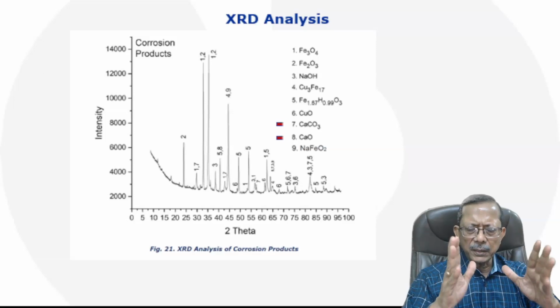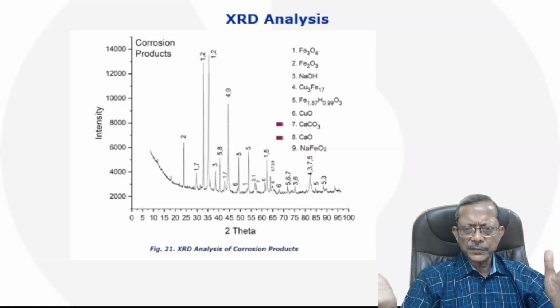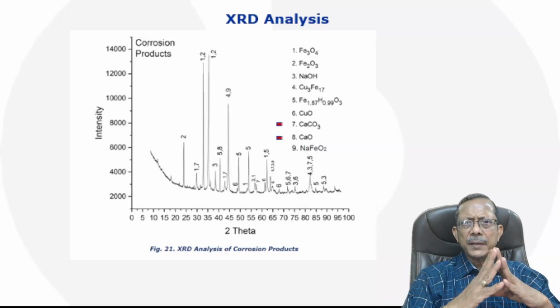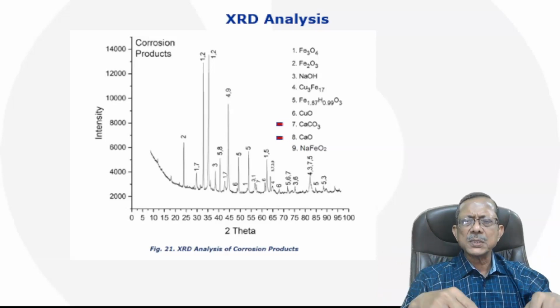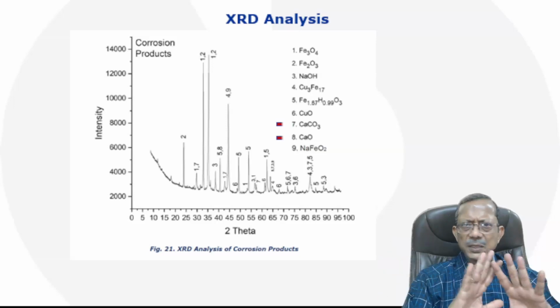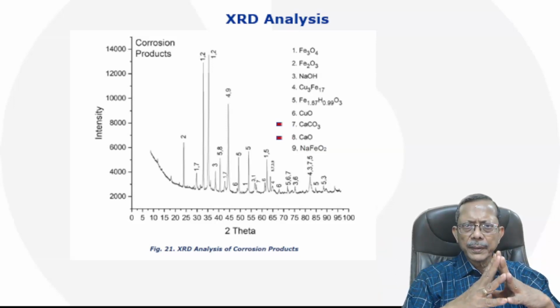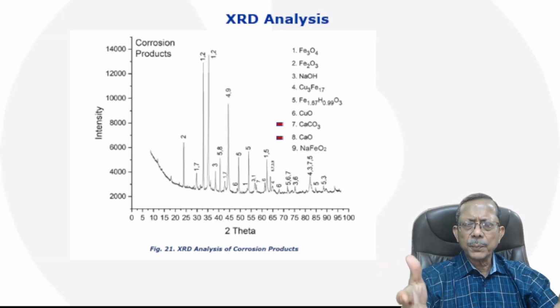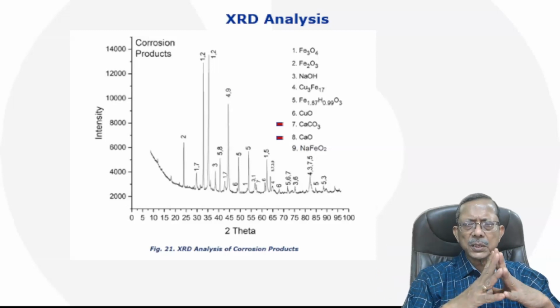So I need to find out the location from where this hardness is coming, where the copper and zinc are coming from. And if calcium is coming into the system, there will be deposit, there is no doubt about it. Below the deposit, there is a chance of, again, corrosion, and particularly with the conductive metal present, there is a highly strong probability of corrosion in the system.